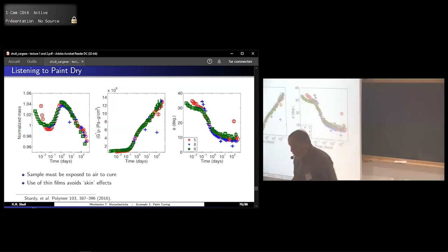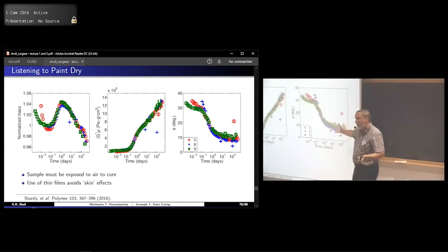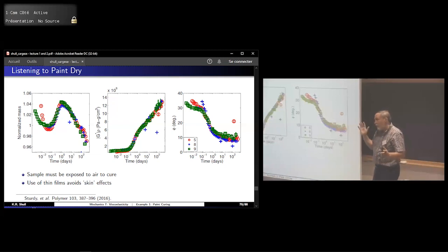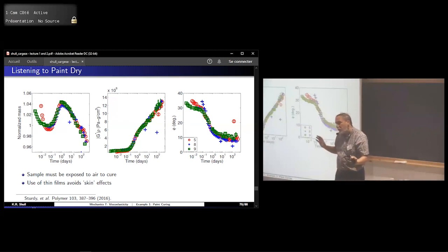What's that? The order of magnitude for the thickness, to prove the bulk property we need some thickness. Yeah, and this is a detailed technique. It depends on the modulus because basically you want the shear wave to go to the top of the film, bounce, and come back. So it depends on the decay length and everything like this. For a glassy film, it's 5 microns-ish, and you don't have a ton of leeway in what that is.